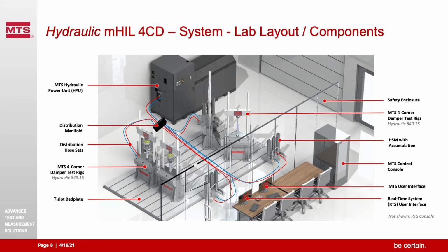Some customers may ask, what's the difference between electric versus hydraulic? If you've got an existing test system that's hydraulic, we can integrate mHIL with that. If you have one that's EMA, we can also integrate with that. If you're buying a new system, we need to talk about the application space of what you're trying to test. If there's applications, for example, for things like durability, we may consider a hydraulic actuation system over an electric system.